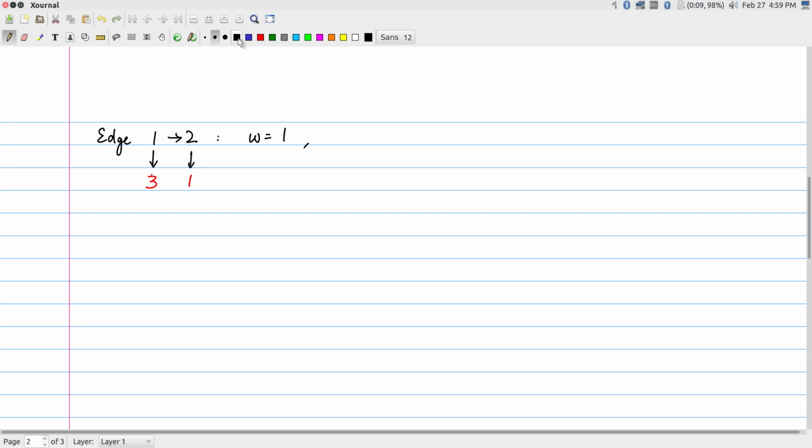So the DF is the time when 2 was scheduled. Let me write that out clearly. It is the time of operation number 2 minus the ending time of operation number 1, T1 plus PA, the pipeline latency of the adder.